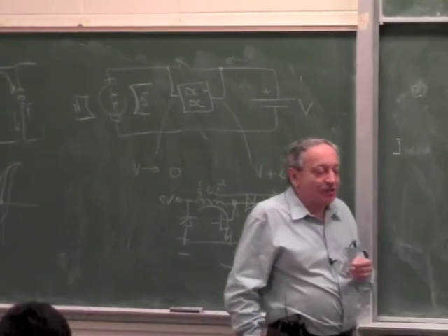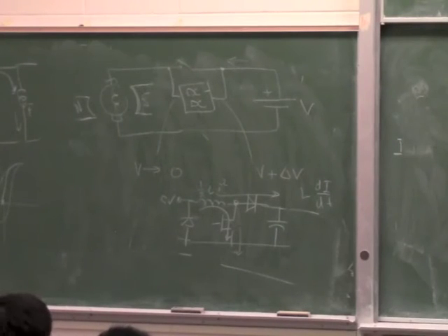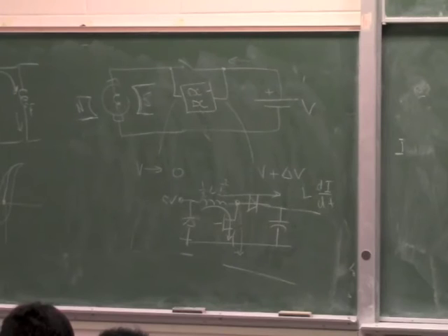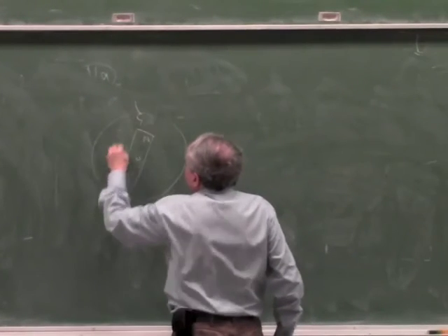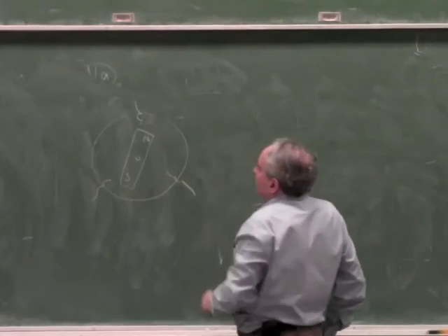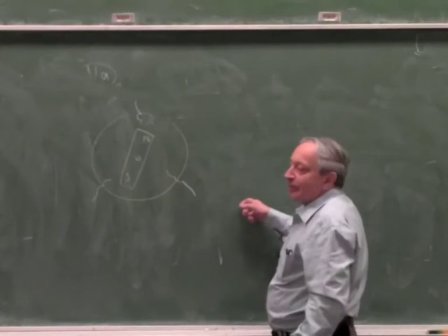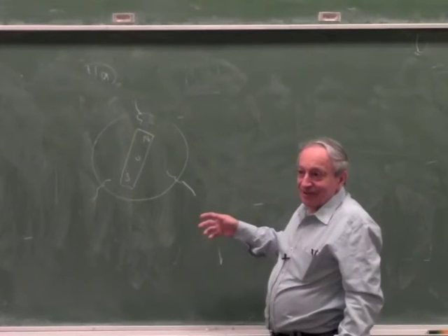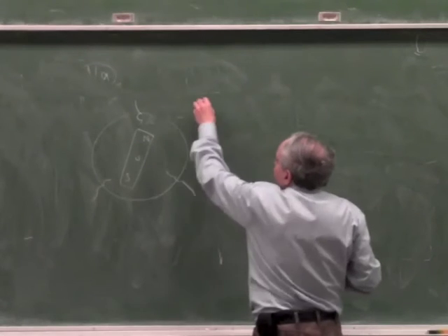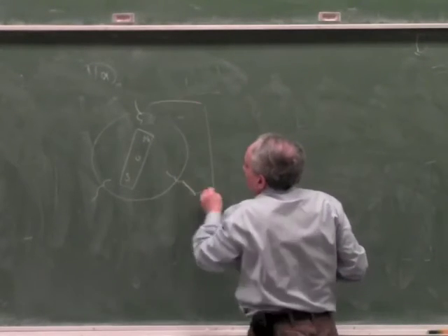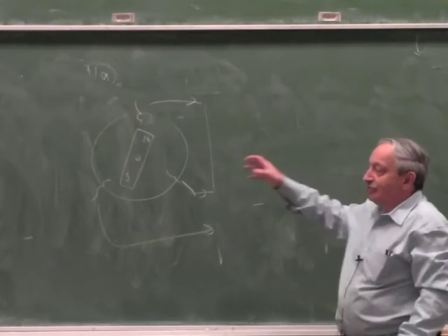In a truly synchronous motor, it's still easy to understand, because a truly synchronous motor, we said, has a magnet, N and S, and has coils. If you don't feed power to the coils and the magnet is rotating, power will come out, because it's still a generator. You have a magnetic field rotating on coils, so 3 sine waves will come out of the 3 phases, and they look exactly like the sine waves used to drive the motor.